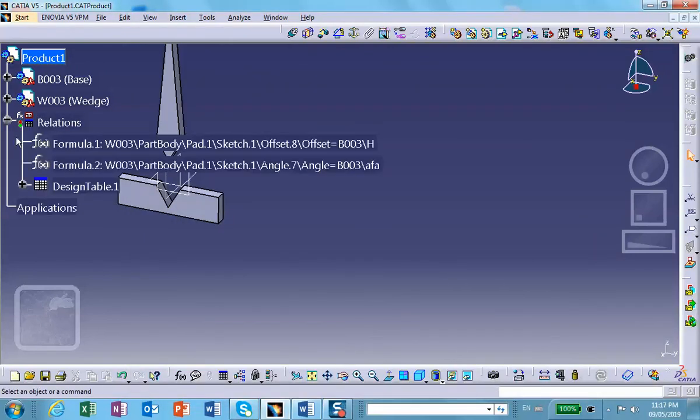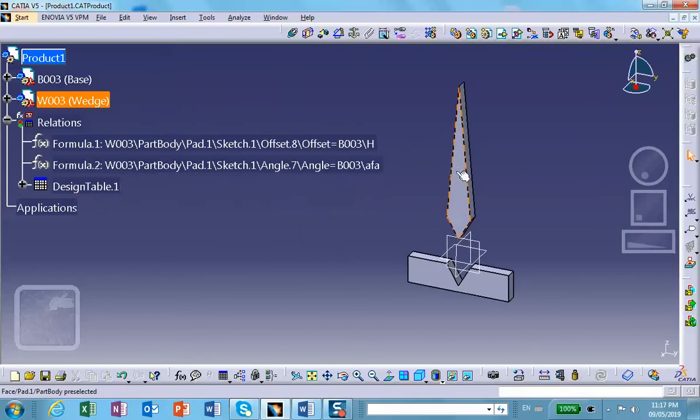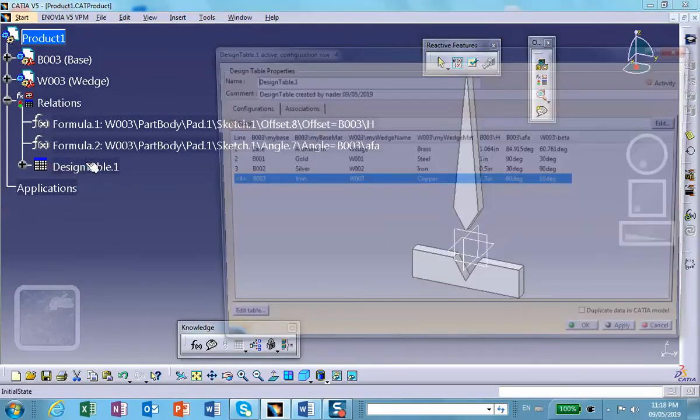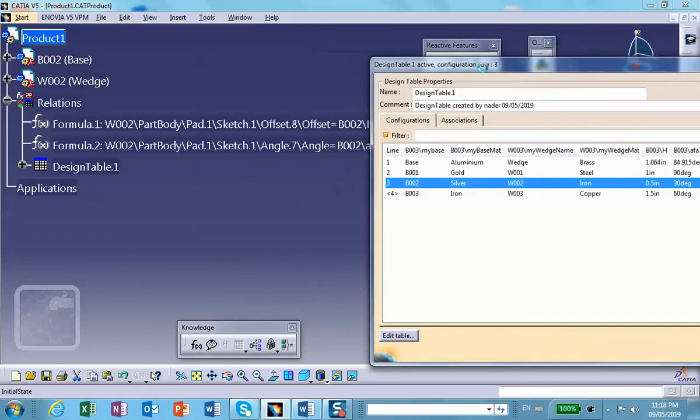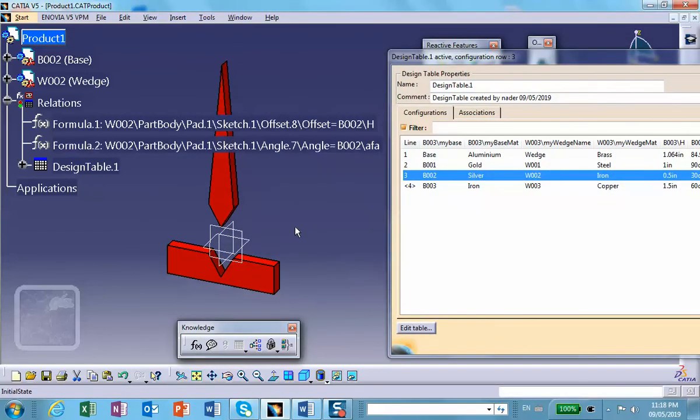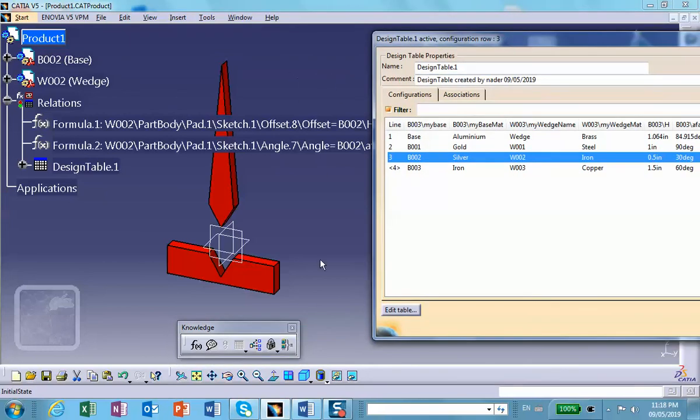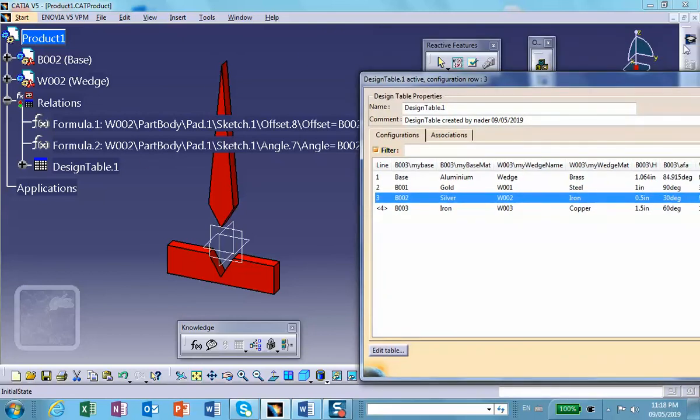You see? Right there. We have two equations. Remember I made this equal to that at the assembly level and this height equal to that height at the assembly level. They're there. And the design table is also there. You double click on it and you can go to the other rows and select it accordingly. Select, and update, where's the update? Well, remember it used to be down here. The only problem is it's not there because I'm not even in assembly.